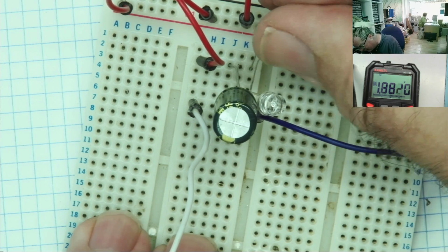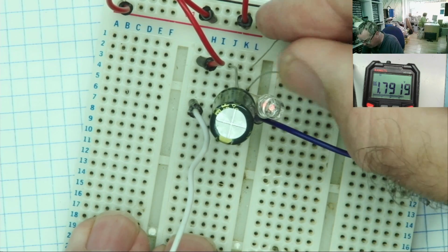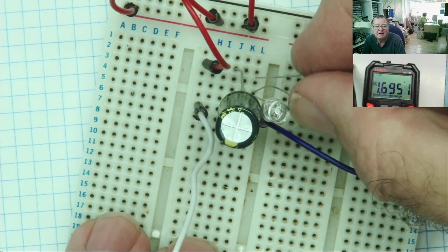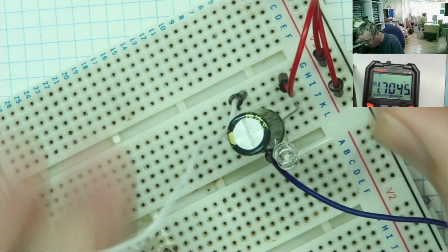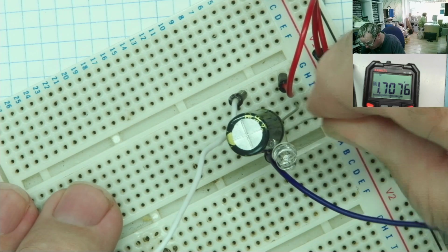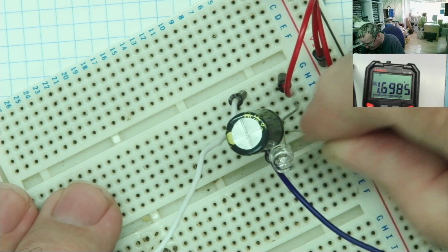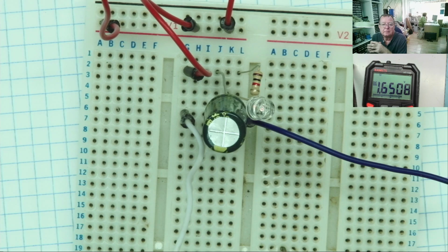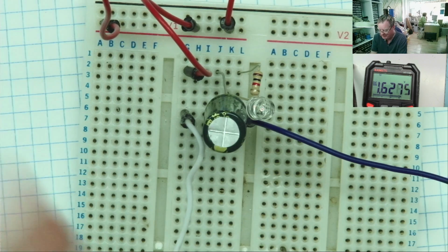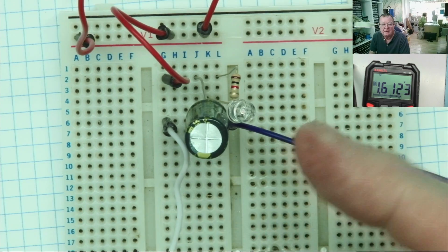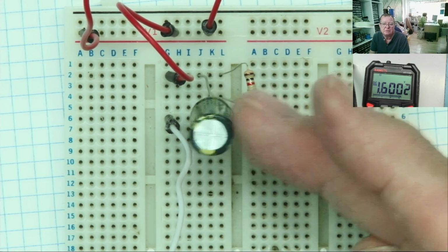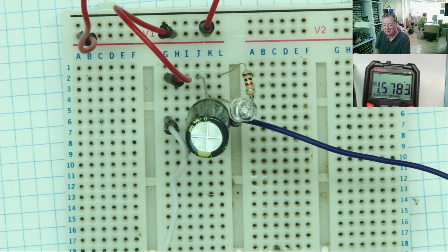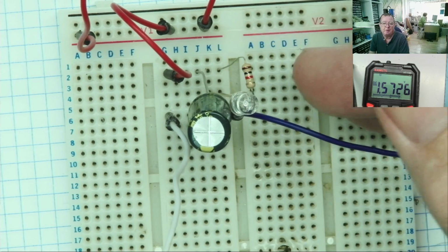Let's connect a higher value resistor. So this is a 1000 ohm. You can see, in actual fact, now the capacitor is discharging again. So the power's off. There was just enough power left in the capacitor to light the LED again. Once the LED lights, it starts to draw current and the capacitor starts to discharge. Another thing you'll probably notice is that the capacitor does not fully discharge. That's because the LED, once it gets down to a certain voltage, around 1.5 volts, stops conducting and stops drawing any power.